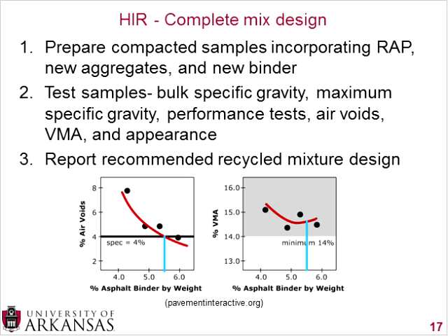Then you need to test these samples that you made for your bulk specific gravity, maximum specific gravity, any sort of performance tests you want to run, air voids, voids in mineral aggregate, and also the appearance. You want to make sure that you're getting a good looking mix. That is one of the new things that is added on to the mix design.